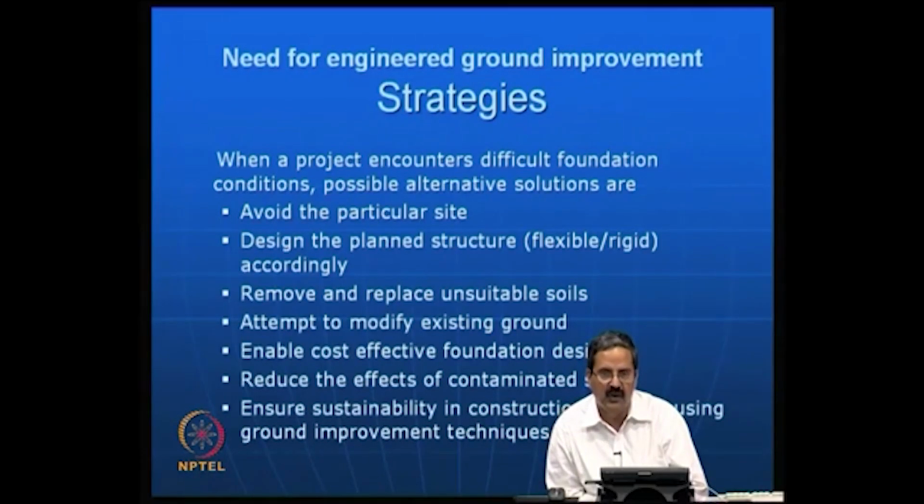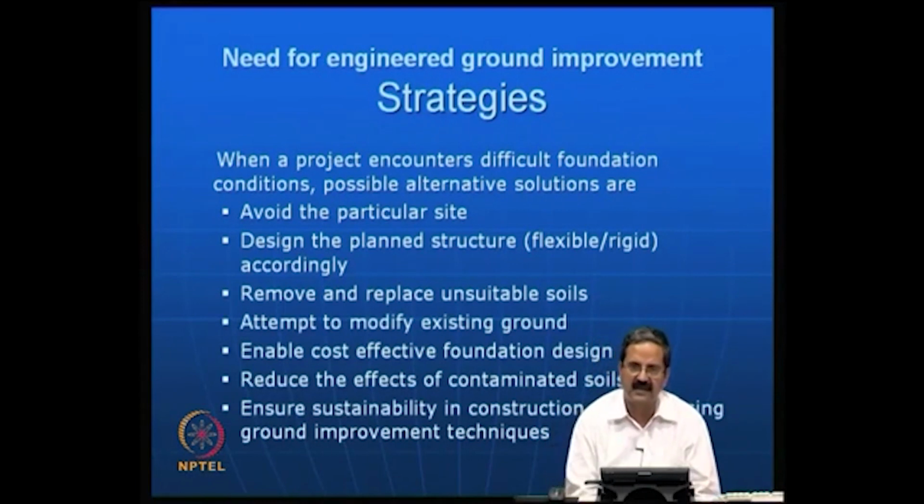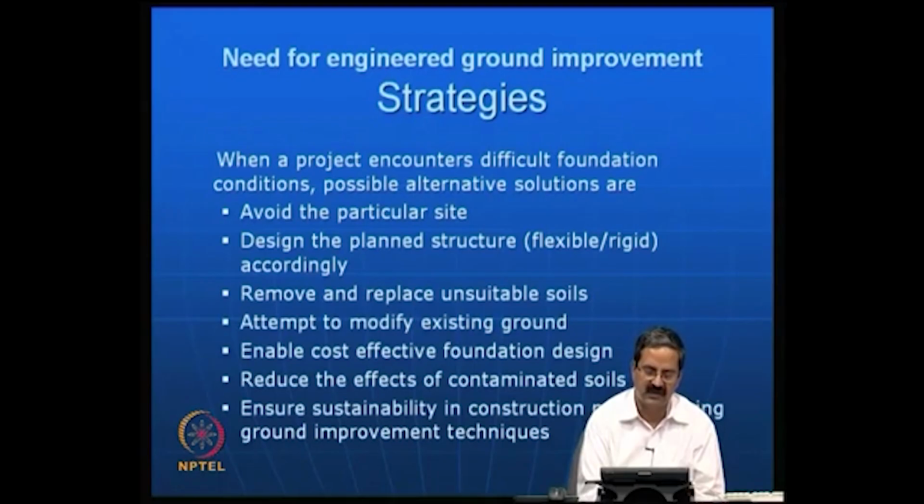Rigid means you have to make very thick sections so that even the settlements that are there do not influence the actual structure. So, the thickness of the foundation will be so huge that whatever small movements occur in the soils may not really impact the foundation or the actual structure. So, this is what we see.